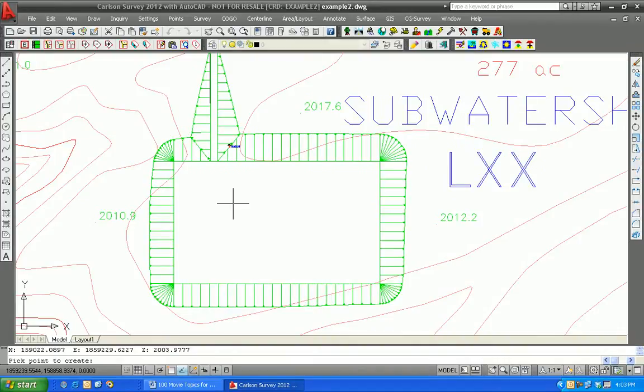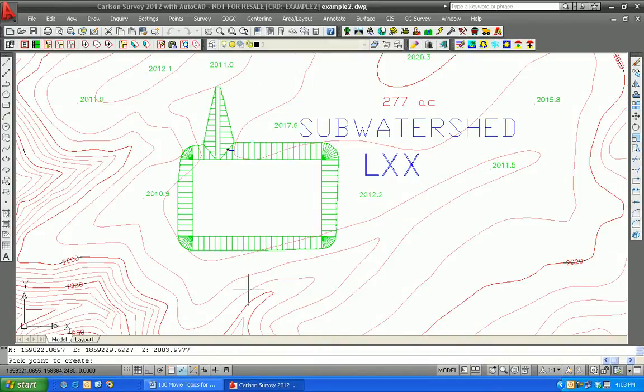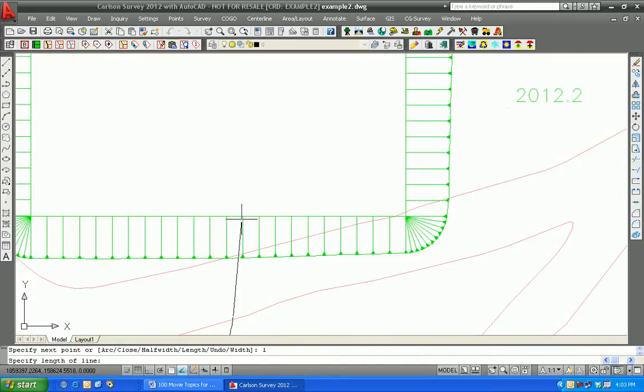So with that done, let's do a more complex road entering our pit. We can draw a 3D poly, or actually a 2D poly, that starts on a particular elevation. Let's start at 2000. We'll sort of angle to the right and then arc our way so we're sort of facing into the pit roughly perpendicular. And then we're still in the polyline command. If you do L for line and a second L, you come off radial, I should say, or tangent to that arc. And let's pick our way into the base of the pit